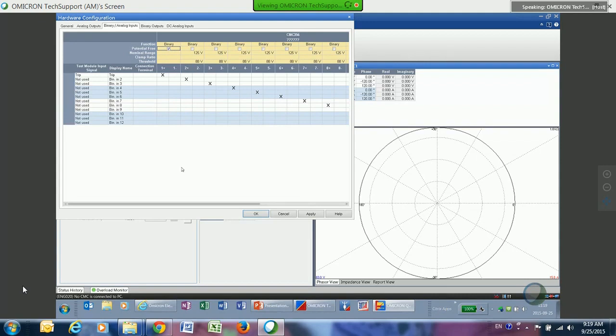On this, you can set up whether you want a wet contact or a dry contact, or basically a potential free contact. By using a potential free and clicking the box, it turns off recognizing any of the voltage inputs that would come into it, and it would be used such as a dry contact. If I uncheck that box, I can now set up what my nominal range would be. So if I wanted 125 volts, which is what my nominal DC voltage would be, that's what I would put there. If you have a 48 volt system, you could put 48 volts in there.